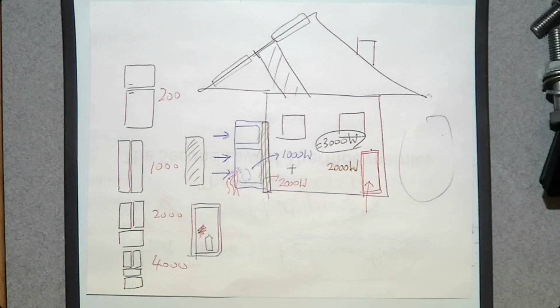Does it make sense? So you are spending 2,000 watts to run this refrigerator, and this is going to be first electricity, mechanical energy, and so on, and finally heat. And you are pumping the heat from the low pressure, cold outside air, and then dumping this heat back into the house. So you're spending 2,000 watts, but what you get is 3,000 watts of heat. That's how a heat pump works compared to a traditional heater. Just trying to give you an idea about what a heat pump is.